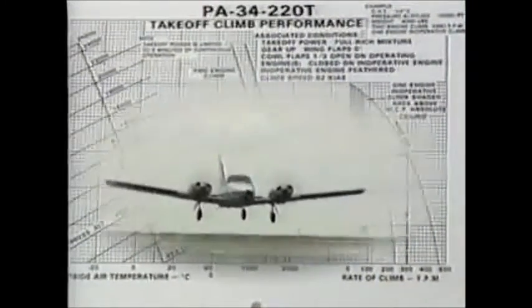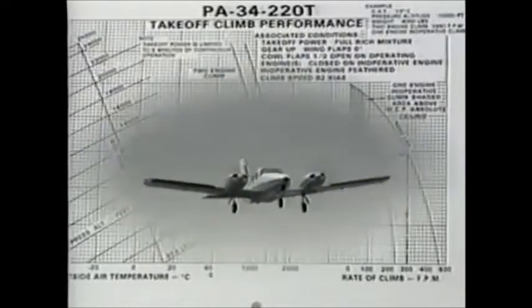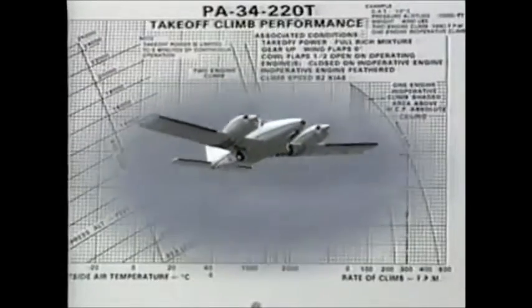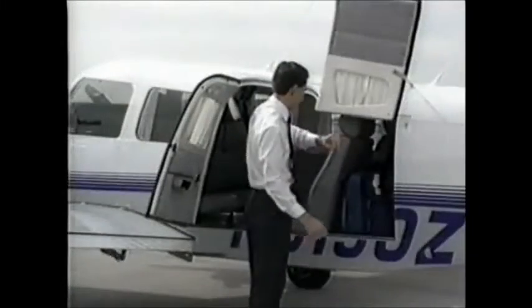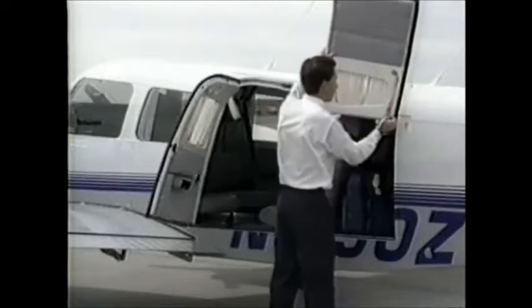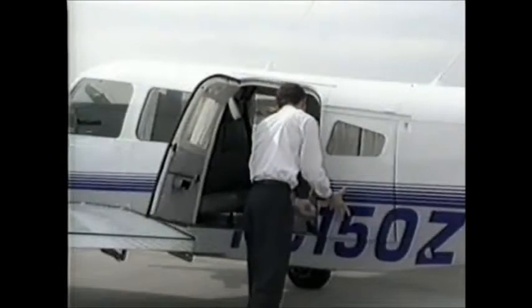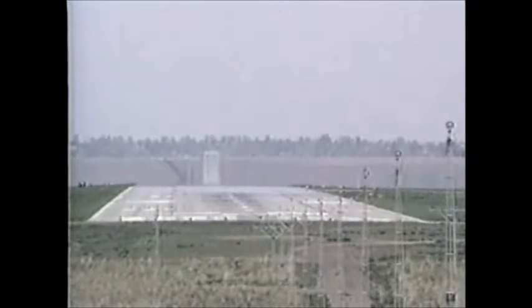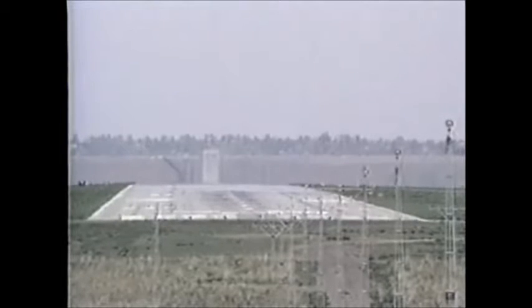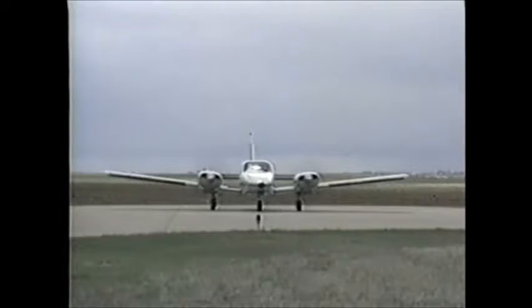If you fly when the density altitude exceeds this ceiling, you may have no option but an off-airport landing should an engine fail. However, you can improve the situation by waiting for better conditions or making the flight with less fuel, passengers, or baggage. You should also make sure that the accelerate stop distance for the existing conditions is not longer than the available runway. Just before takeoff, review the procedures and airspeeds to follow in case of engine failure. This includes a plan of action to avoid obstacles if your climb performance is suddenly reduced.